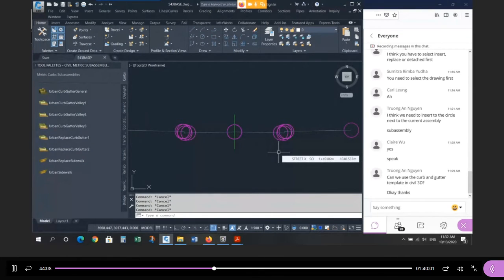The underground layers, the volume of asphalt and granular and concrete for curb and sidewalk, I'm going to do that manually. I'm just going to get areas times depth. You'll see that the estimating process is a little simplified. For roads, it's useful to have all the underground layers, but for subdivisions, it's not that. It's more trouble than it's worth. So I don't know too many people who use it for local roads. Really, this is all you need. Okay, and you'll see what the purpose of this is in the second half of the course.